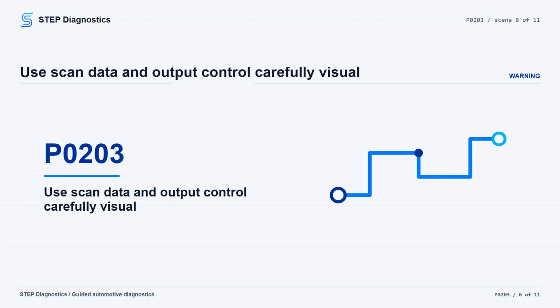Confirm programmable parameters are correct for the function being tested, and if a DTC needs to be resolved first, handle that fault before moving on with symptom-based checks. Then, test the inputs, test the outputs, and check for module software updates. If a commanded output works normally, that points you back toward the inputs and circuit conditions feeding the decision.